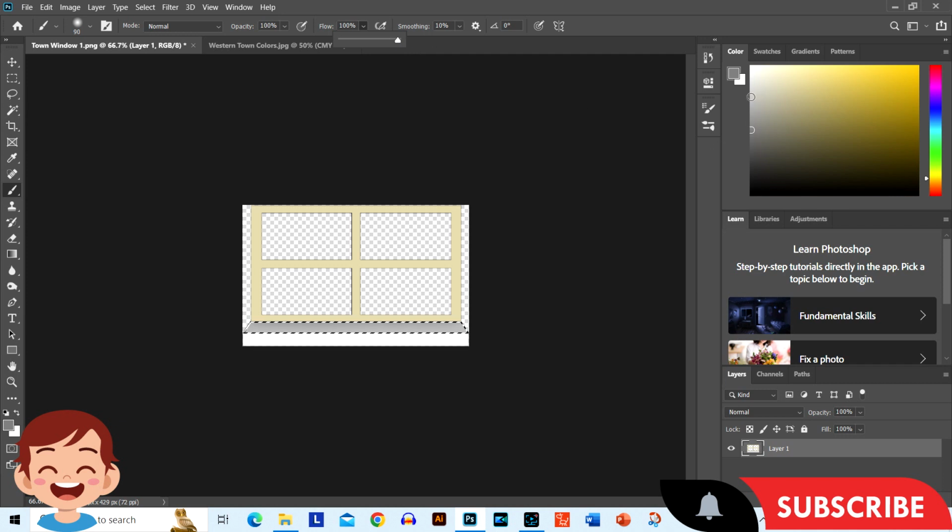Going to move this up a little bit. Grab my magic wand tool. Click on the space I want to select. Press B on my keyboard. Use my bracket keys, make it a little bigger. And that looks awesome. Now if I want to make this transparent, I need to take a further step.